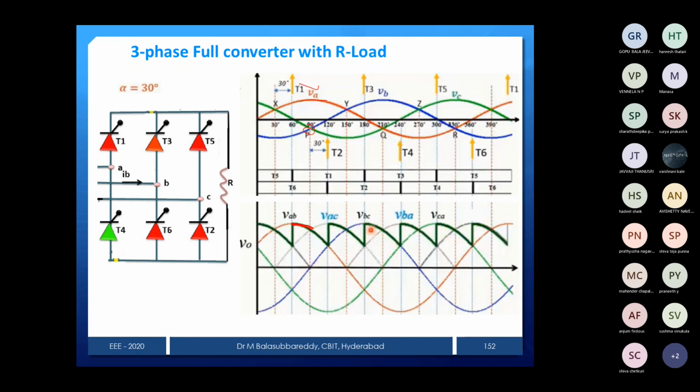From this crossover onwards, C phase is more negative than B phase. But why did I keep it as B phase only? Why am I not transferring to AC after this crossover? Why do I continue with AB only?